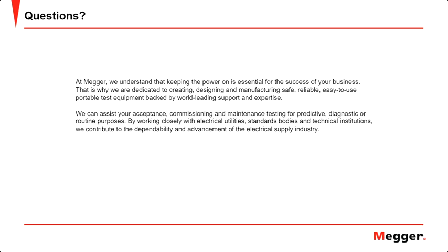Thanks, Chase. Yash, I recently read a paper, which of course I can't find now, that indicates DC insulation, PI, and DAR testing were not providing valid results on medium voltage cables and suggests they are no longer applicable. Can you elaborate on the effect of PI and DAR on medium voltage conductors, and if this is still considered an acceptable testing format? If not, why? PI and DAR are still relevant if you are just testing the insulation purely.